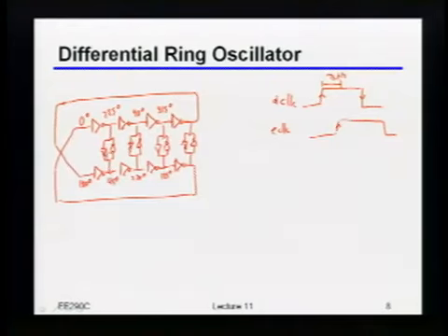You have more capacitance, right? This forces you to size things with a certain ratio, because if you don't, then again, the whole thing may not work. So indeed, it basically slows you down, okay? And remember, if I'm trying to do, let's say, a 10, 20 gigabit per second link, and I wanted to do it with a ring like this, I really want to push the frequency of that oscillator, because I want to get this thing to go just as fast as I can go.